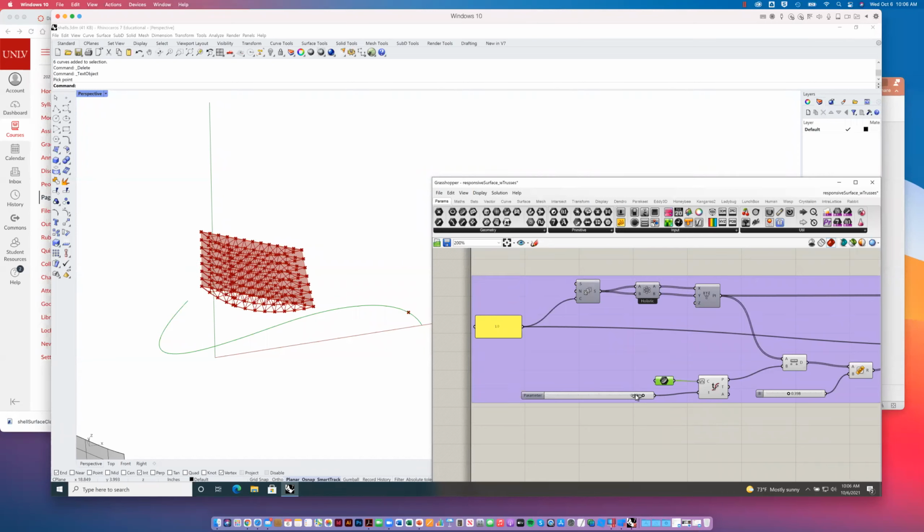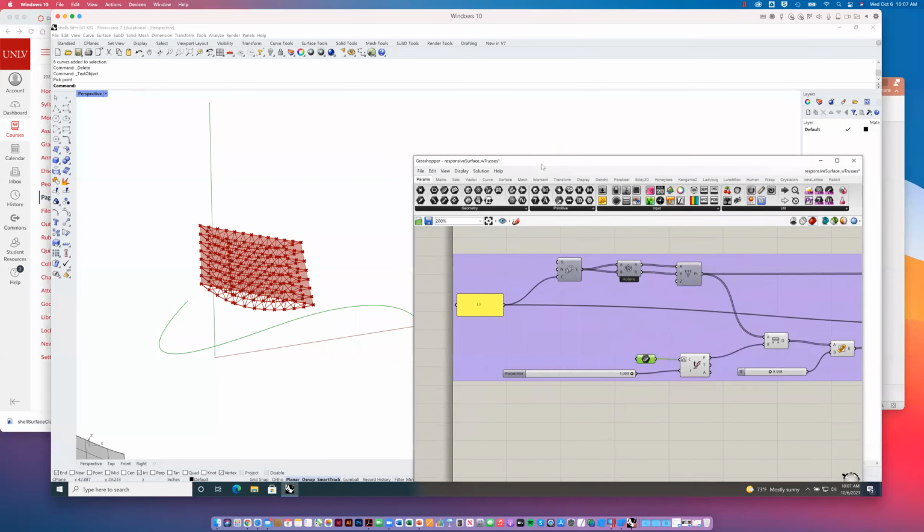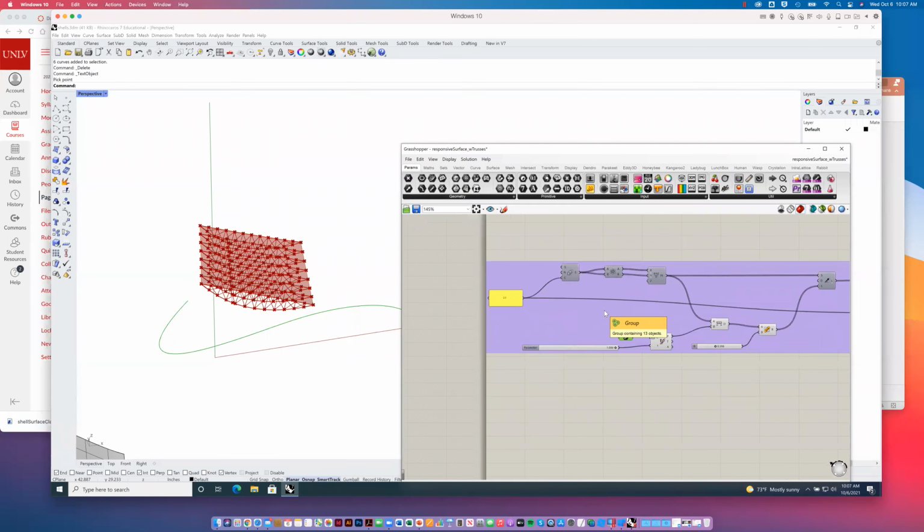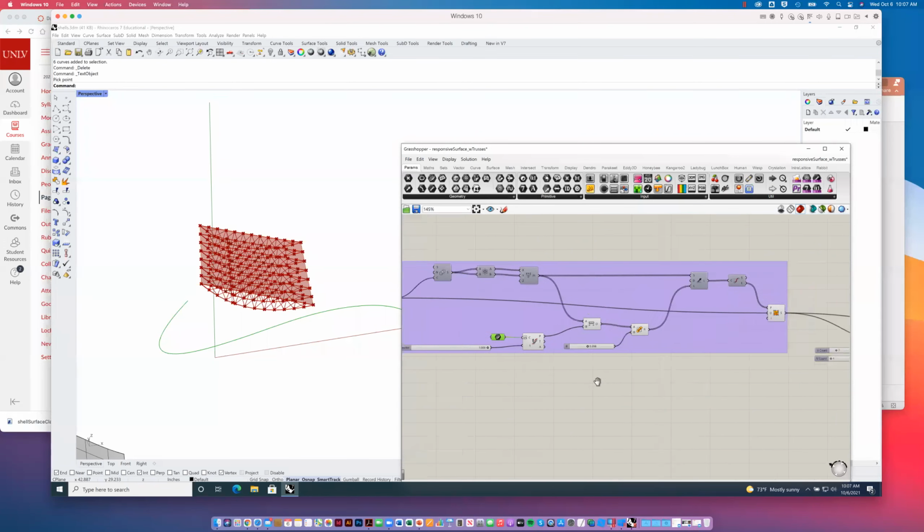So again, here we're making a surface from a set of points, right? And those points change their Z direction based off of this attractor point. That point is something that we generate. It's a fairly common ingredient in parametric models. But again, it's this idea of attraction, or the distance or proximity to what we're influencing, the geometry that we're changing, to this attractor point. Okay, and don't worry, you'll use attractor points in the future, no doubt, whether it's for shape or patterning or whatever.